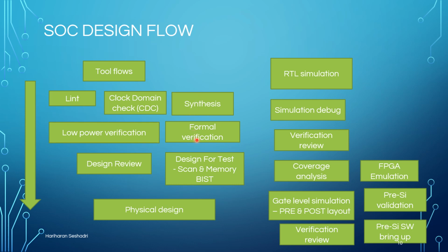Then we do something called formal verification. There are two types of formal verification. We'll talk about what is commonly used in the industry today to check the RTL generated in the previous slide: is it correctly mapped by the synthesis tool? Formal verification takes constraints as input, RTL code as input, and the netlist from the synthesis as input. It checks whether they are equivalent or non-equivalent.